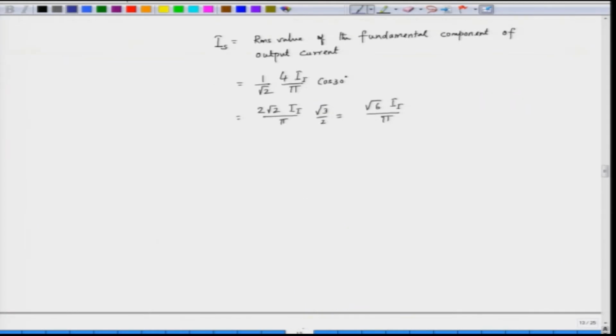So, if we apply this principle to the induction motor, we can draw the equivalent circuit of the induction motor. We have the stator resistance and reactance, then rotor reactance and the rotor resistance here. So, this is our equivalent circuit of induction motor, and we place our magnetizing branch here. We do not approximate, we draw somewhat exact equivalent circuit. The losses are included in the output.